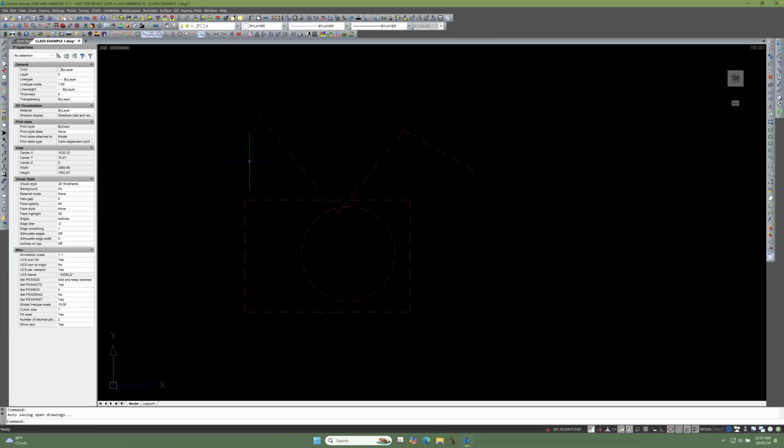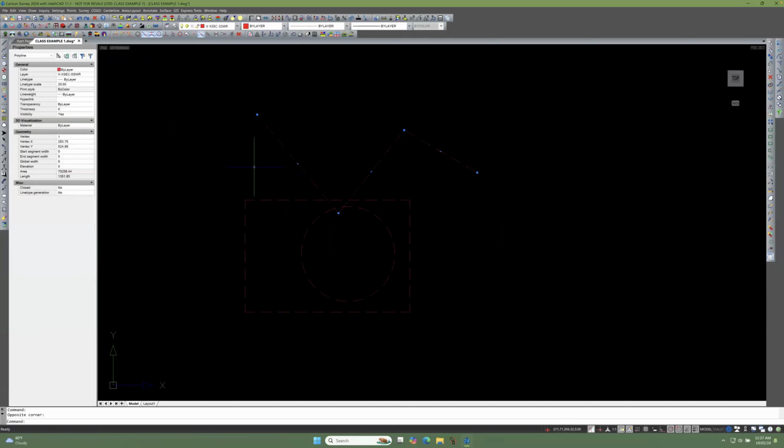Okay, so now what I want to do is let's erase the things that we've drawn. If you've doodled and got a bunch of stuff that you want erased, there's a couple of ways to do that. You can just select something. And by the way, once you select something, you get grips on it. If you hover the mouse over a grip and then click it, you're going to change its location. If I hover here in the middle, you see it moves that whole segment. If I click on the vertex, it moves just that point.